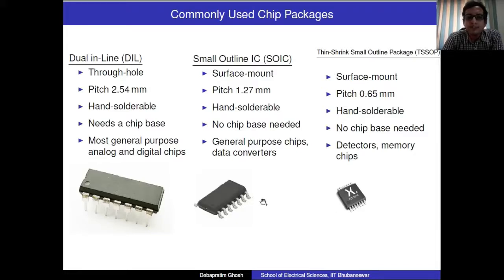Now all of these things are hand solderable, although you will need some amount of expertise for the SOIC and TSOP packages. So if you develop a good amount of expertise in soldering, you could do this yourself. I have also listed some applications of each of these packages where they are commonly used.